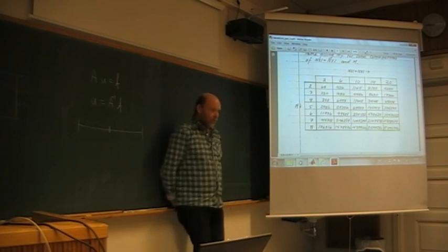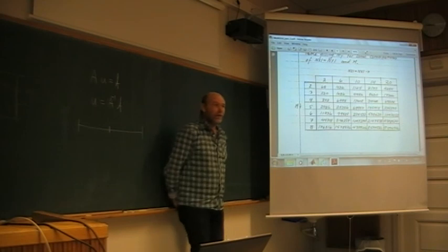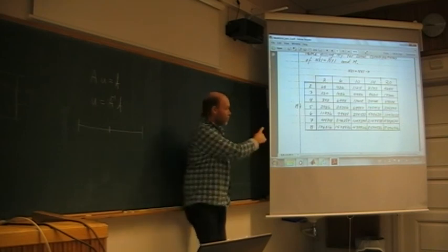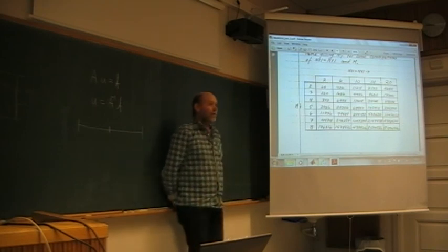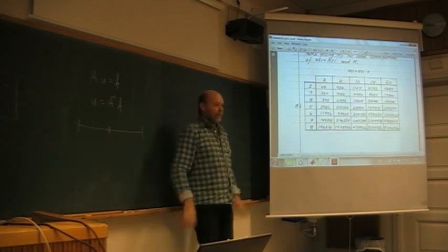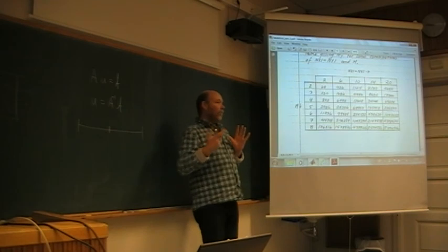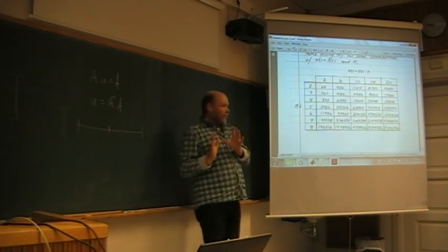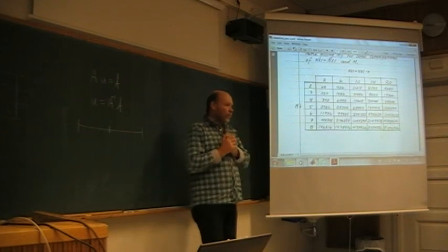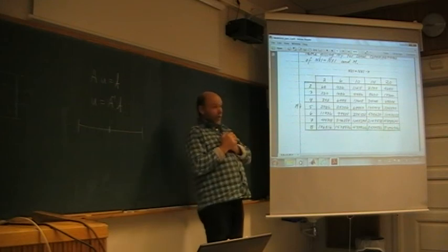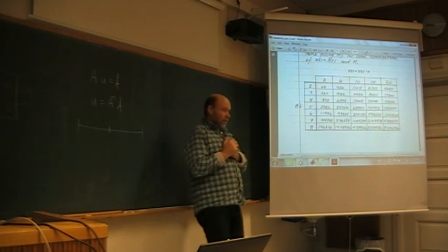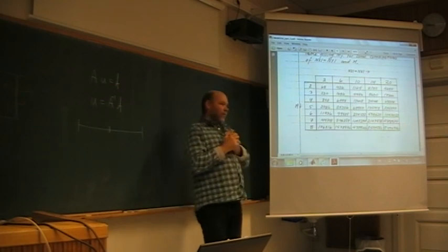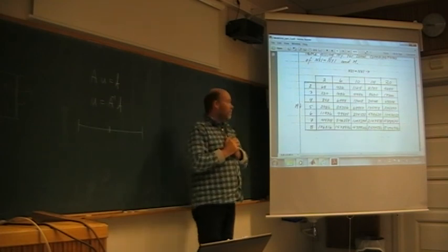So yes, typically a Poisson equation for the pressure. So you don't take the entire Navier-Stokes and push it through multigrid. There's no point, because most of it will actually be a parabolic problem. You update the velocities, but somewhere inside there you have to solve maybe a Poisson equation for the pressure, like we did with the Sola algorithm, or other algorithms.